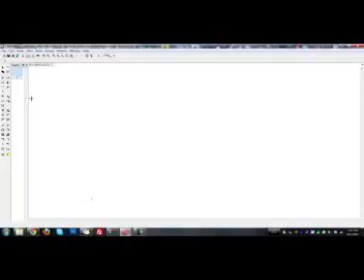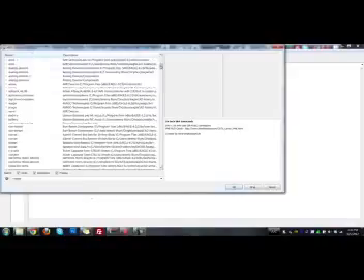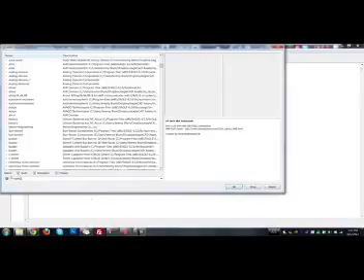In addition to the battery, I'm also going to use the footprints that they supply for 0805 LEDs, resistors, and capacitors, just because they're there and it's easy. But you can get those from other libraries as well. Click the Add button in Eagle in order to start adding components to your schematic view. Once the library window opens up, you can see all the libraries that are available to you. There's a lot. Be sure to use the search functionality if you're looking for something in particular. You can enter a search term here.